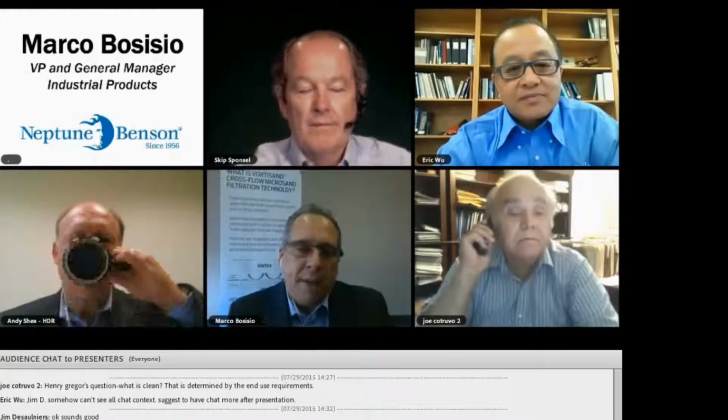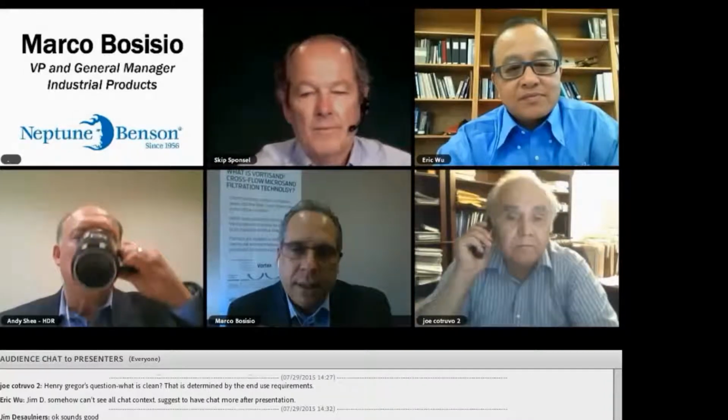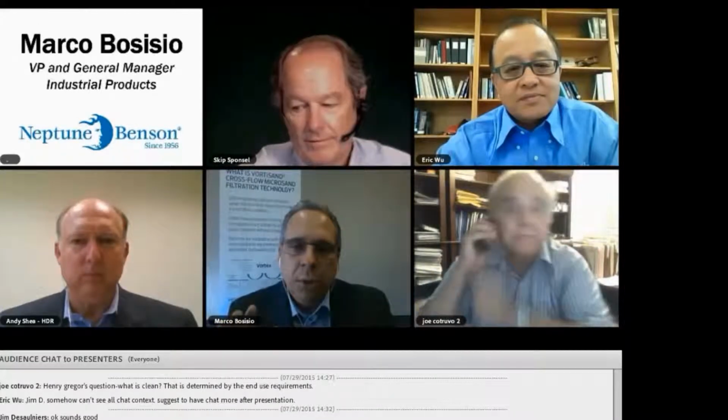But we do have some systems like air scouring available to make sure the media is always clean, even if there's some BOD in there. I would say that if a designer believes that a regular multimedia filter or a disc filter can handle the type of effluent that is trying to be filtered, then our system will definitely take it as well. Thank you. Andy.